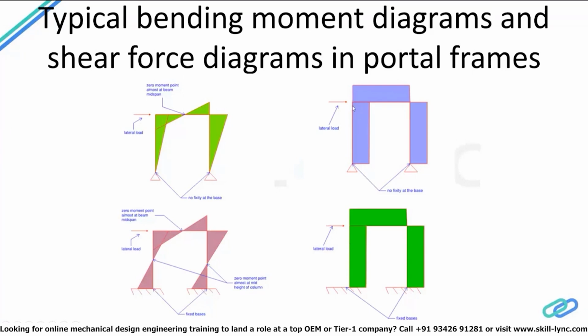And then from a shear force standpoint, whenever you apply any point load, obviously you are going to see these horizontal reactions on the support, right? That horizontal reaction that's developed on the support is equal to the shear force, or rather the shear force in the column is equal to the horizontal reaction that's developed in the support. So for example, if this was a roller support instead of a pinned support, in that case, the entire horizontal reaction would be taken by this support, and there would be no horizontal force or reaction on the support at all. So that means there will be zero shear force on this member, and the shear force here will be equal to the total lateral force that's applied.